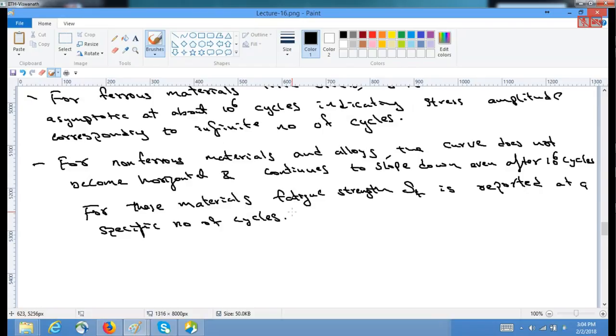Further, so far we have done the endurance limit with the notion that our mean is at a zero value, that is, a complete reversal of the load. But at times there will be non-complete reversal of the load. In those cases, the behavior of the material is much different from what we see in complete reversals, and the design for fluctuating stress with non-zero mean has to be done by creating an offset or something like that, which we'll do in the subsequent classes.